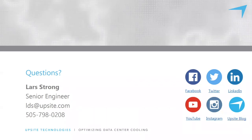Yeah, there's a few things I can say about that. Obviously, some manufacturers of IT equipment pay attention to this more than others. The standard does exist in the industry, not necessarily by the Uptime Institute, but the standard is flow from the cold aisle to the hot aisle, and more manufacturers are getting on board with this. As I mentioned, problems can be created by people that mount the equipment backwards. Sometimes that's just a lack of understanding of the process, and it really points to the importance of making sure that both the IT side of the business and the facility side of the business have a shared understanding about the process and how cooling works, how cooling airflow optimization works, and what is necessary to follow those best practices.